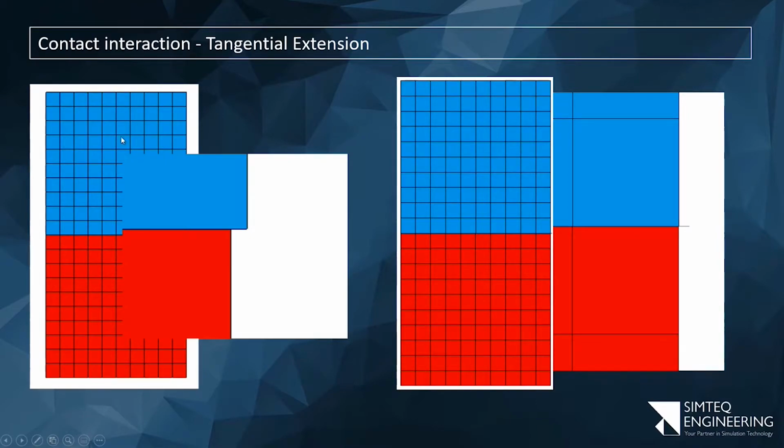So typically, if this was, let's say, a rubber part, I apply a load, and due to that, this expands sideways and these start falling off, and you start running into these kinds of issues. So as you can see, a perfect contact algorithm that automatically does everything doesn't really exist. There are always these little exceptions that you have to take into consideration, and the purpose of this is to try and look at those.